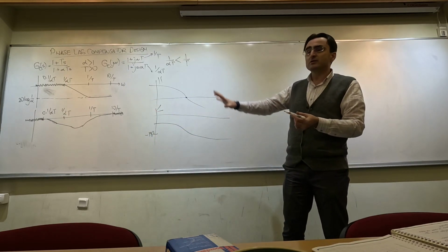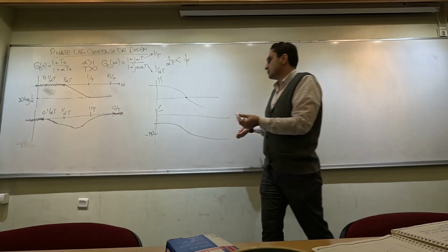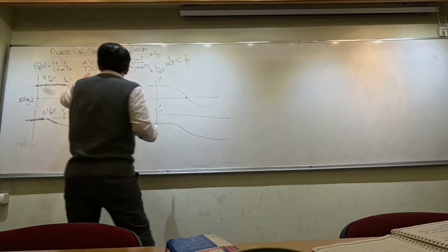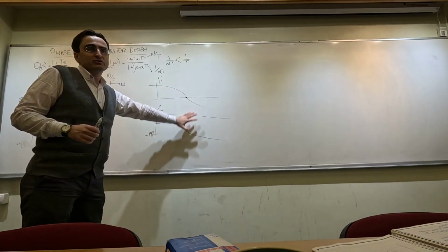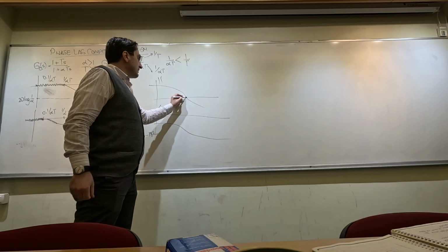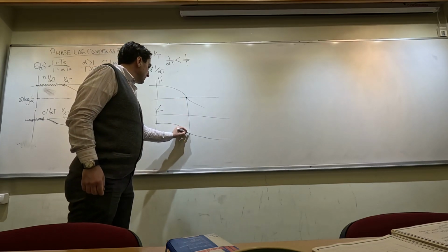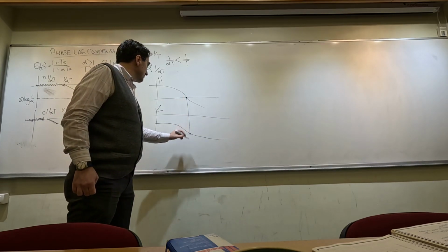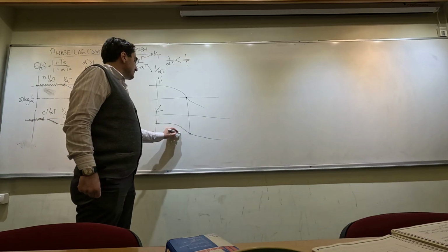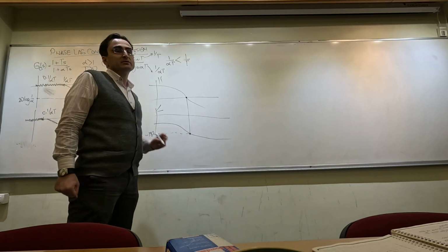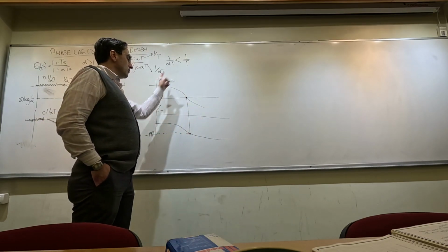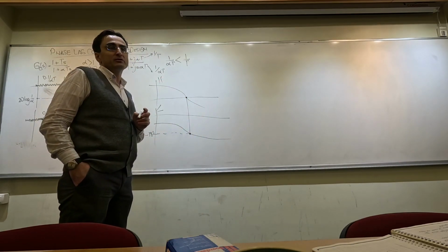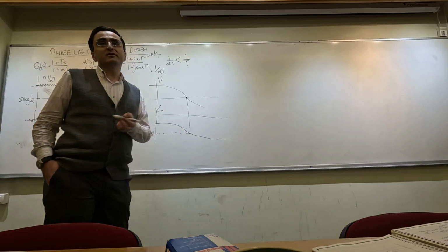And when I look at the closed loop systems, I can determine, for example, if this compensator is not in the open loop, what the phase margin of the system is. So this is the gain crossover frequency, and I can read the phase margin here. Let us say that this is approximately at minus 180 degrees, meaning that the phase margin of the closed loop with only this open loop transfer function is going to be approximately 0 degrees.